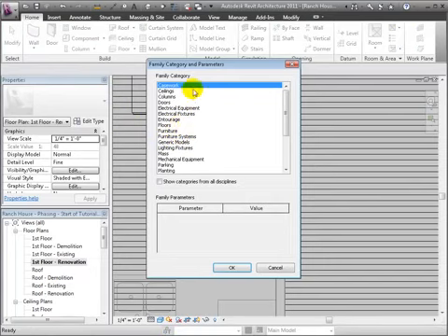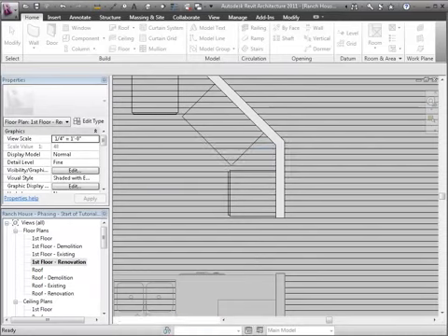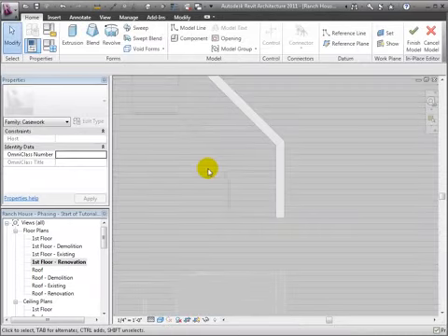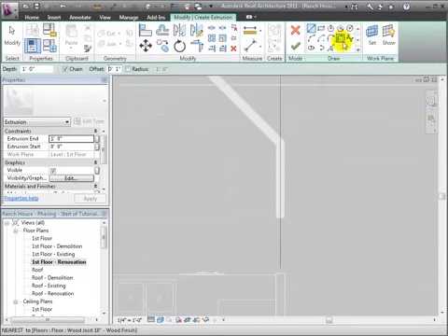And we'll do that as a model in place component since it has a custom shape. We'll call it the island counter. And using the pick tool, it'll be a solid extrusion that I can draw using the pick tool, defining an offset of 1 inch off of the base cabinets to give us a small overhang.